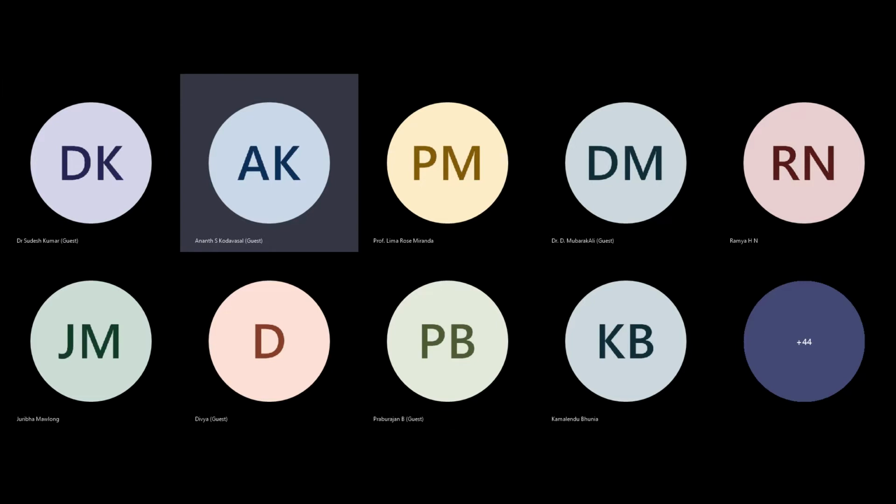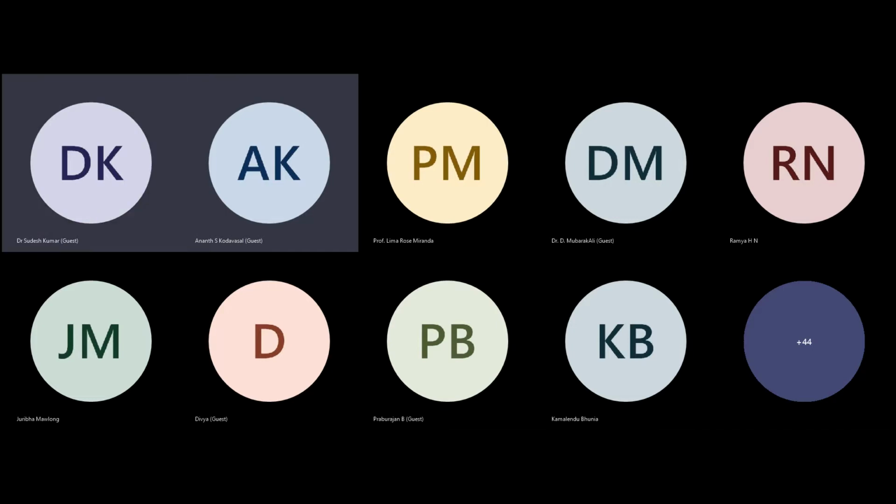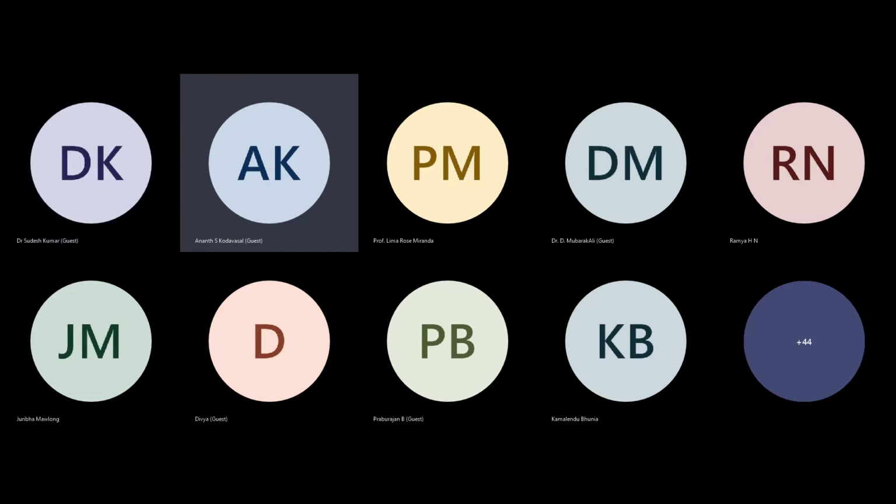Again, there are anionic polymers, non-ionic polymers, and cationic polymers. Typically for settling and dewatering, more or less the same category of solid liquid separation. Basically, they separate solid and liquid, whether it is plain sedimentation settling or it is dewatering using a centrifuge and things like that. The unit process is still solid liquid separation, and cationic polymers are best suited for this.